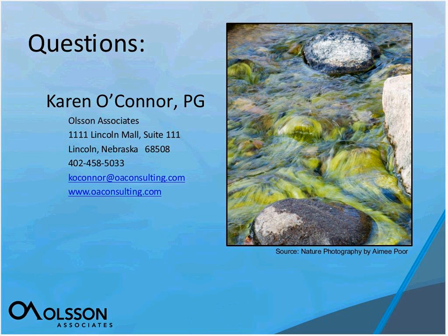Another question is climate change. Does the model have the capability to model long-term impact of climate change? That's a really good question. What we tried to do in simulating those 20 years was look at the climate changes over a period of time where there was a drought period. And as they showed in one of the slides, you could see the water table hydrographs from the USGS well from 2001 to 2006 did show a decline during the drought period. We also had some highs in earlier parts of that modeled period. But yes, that's the intent, is to look at changes in climate based on historic record.